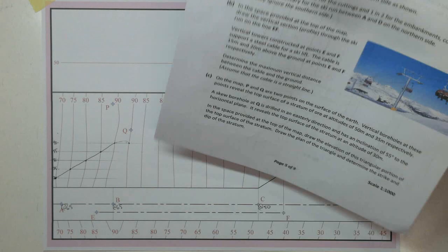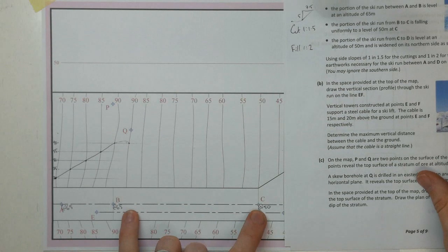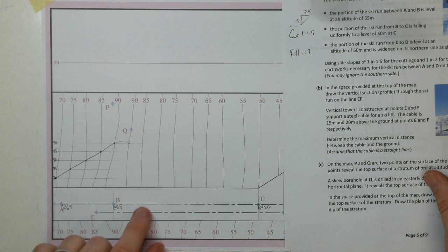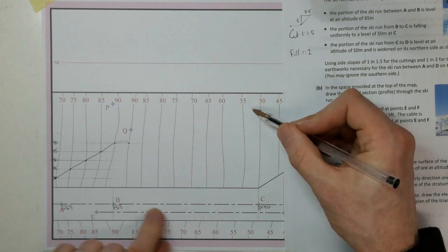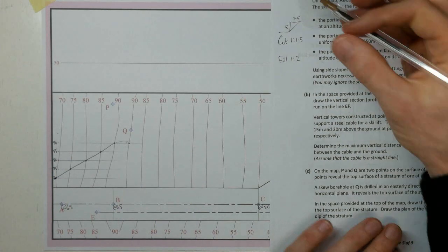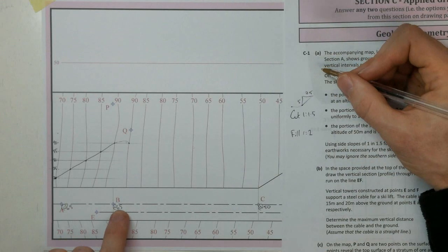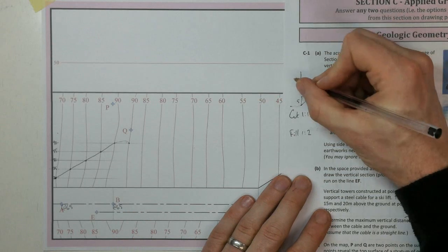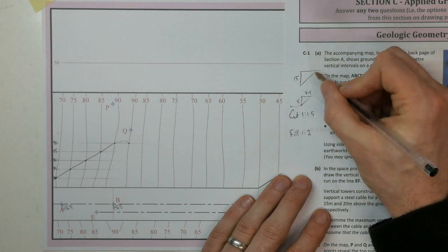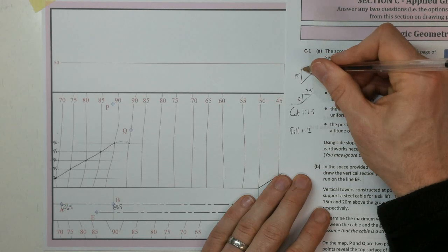We need that, just leave that for now. Then we're going from 65 to 50. We're sloping down. We've got heights of 90 down to 55. So we're going to be cutting down here again, using a cut cone. Now, just to make my sketch here again to help me, I'm traveling 65 to 50, so I'm going to be traveling down 15. So using our cutting of 1 to 1.5, that's going to be 15 down.